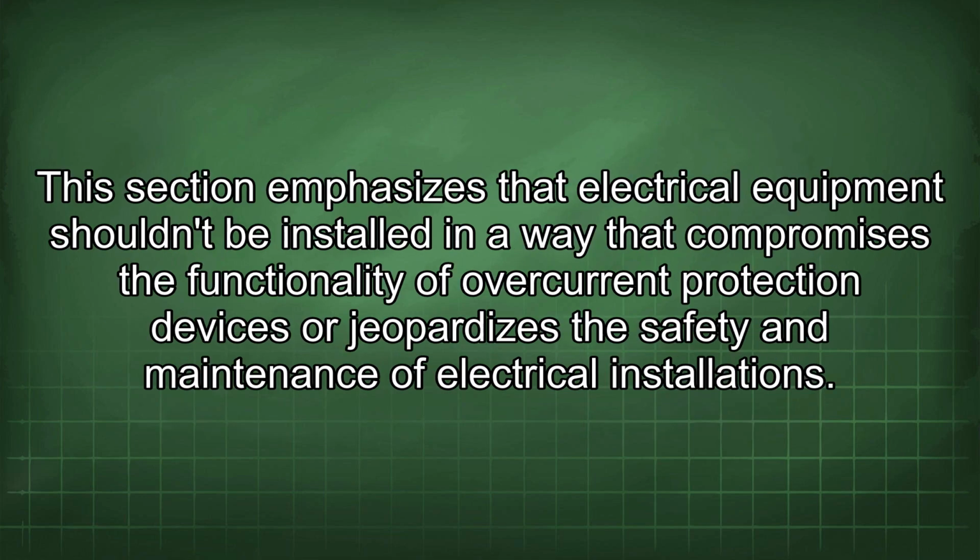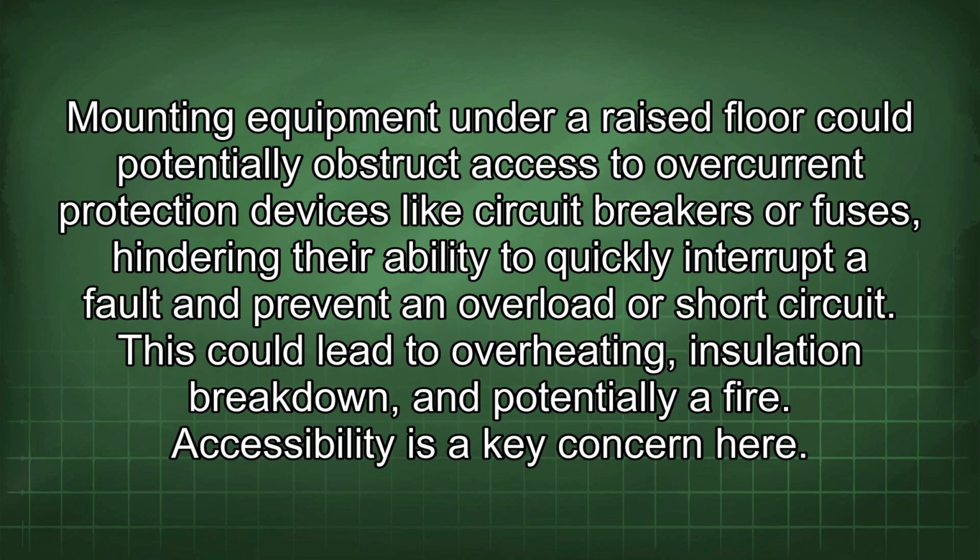This section emphasizes that electrical equipment shouldn't be installed in a way that compromises the functionality of overcurrent protection devices or jeopardizes the safety and maintenance of electrical installations. Mounting equipment under a raised floor could potentially obstruct access to overcurrent protection devices like circuit breakers or fuses, hindering their ability to quickly interrupt a fault and prevent an overload or short circuit. This could lead to overheating, insulation breakdown, and potentially a fire.